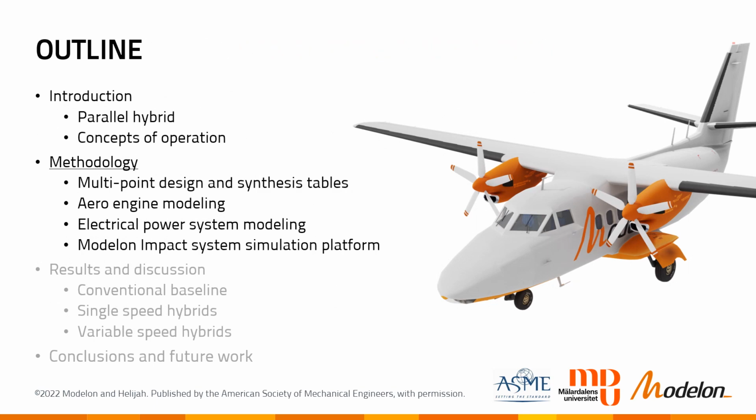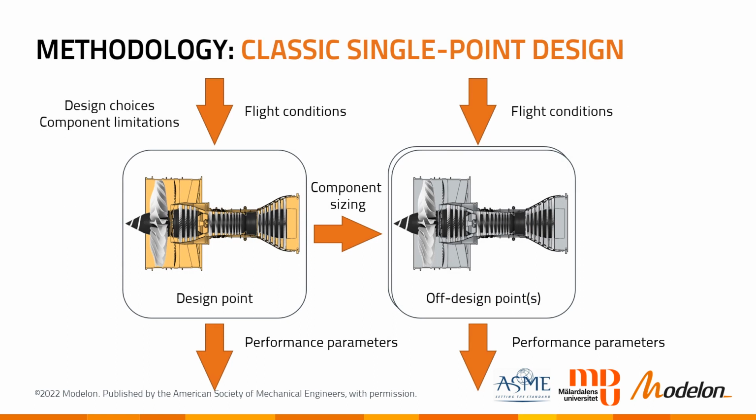Let's talk about the methodology then that we've applied. This slide illustrates the classic single point design, and as most of you know, a single design point is used there to define the sizing of all components as you see it to the left, and then many off design points are simulated to yield different performance estimates on different flight conditions.